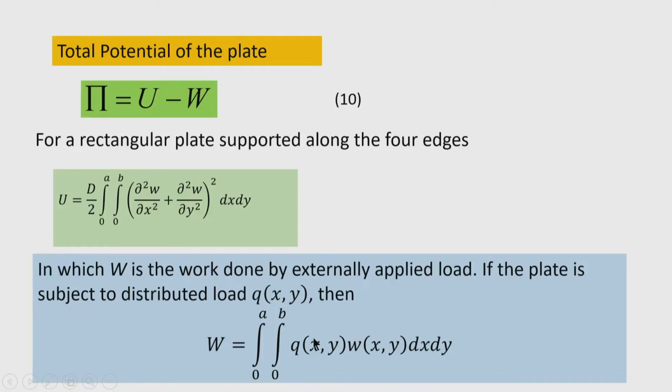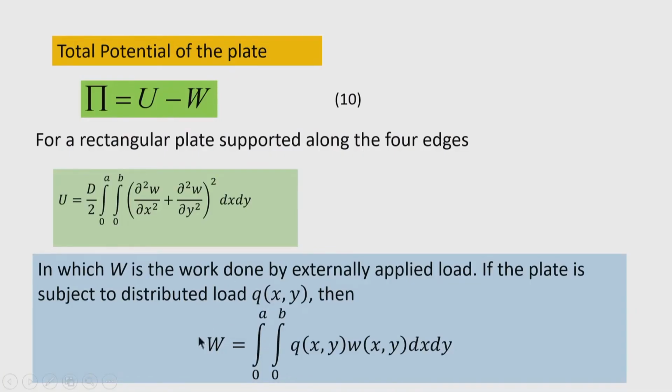based on the reason that the deformation does not change during the application of the load, or the load does not change while the plate is undergoing the deformation. So, therefore, in case of W we have not used the factor half.